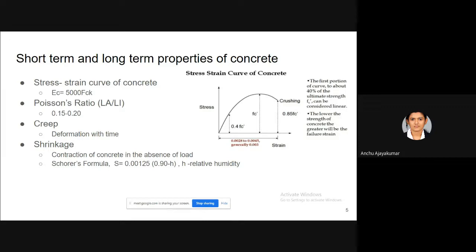He tries to resist so as not to fall down, right? That internal resistance offered by him, that internal force offered by him to resist the push that I have given, is called stress. So in concrete, it is nothing but the internal resistance against the load applied, or the internal force developed within the body against the force applied. That is stress. Strain is nothing but the deformation.